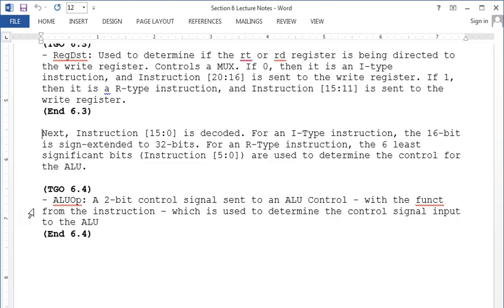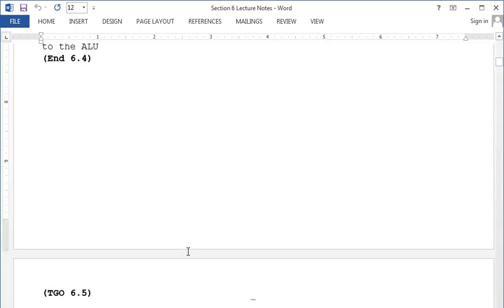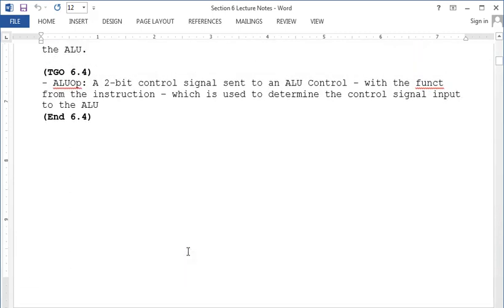And we use that to determine which operation, because remember we have a 16-to-1 mux to multiplex every value on the output of the ALU, right? So we need to have a 4-bit value coming from the ALU controller going straight to the ALU. I'll give everybody a split second to write down the ALUOp.